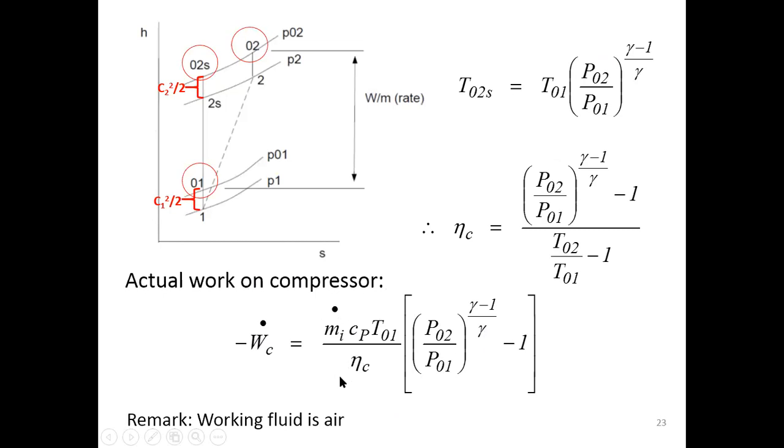Remember, all the working fluid in here is air. In the supercharger, all the working fluid is just air. Okay, so this is how we can calculate the actual work that we need for the supercharger, which is the amount of work that needs to be delivered by the engine. In terms of supercharger, the engine has to provide this much work to the supercharger.